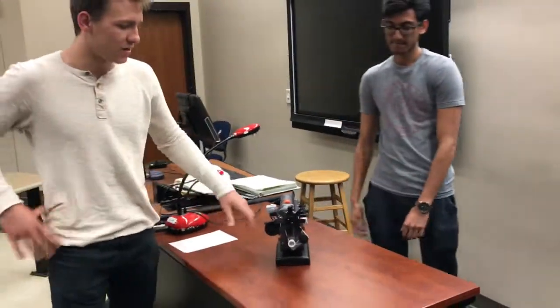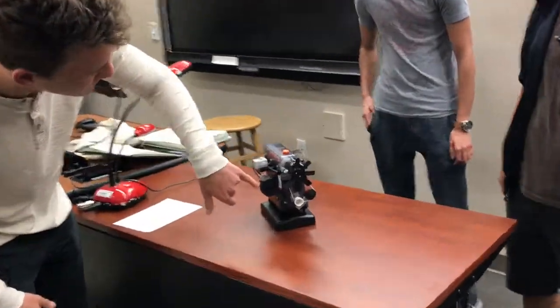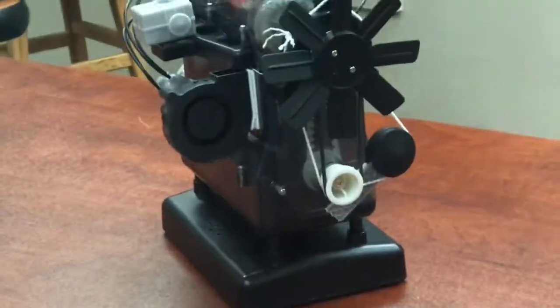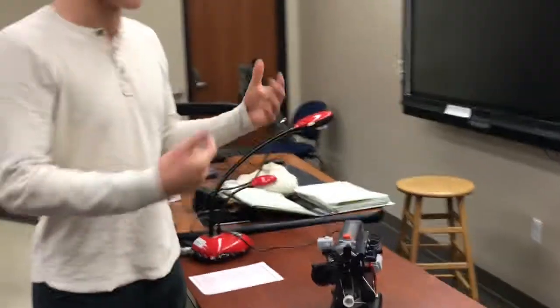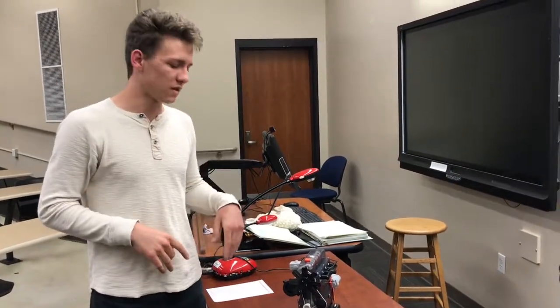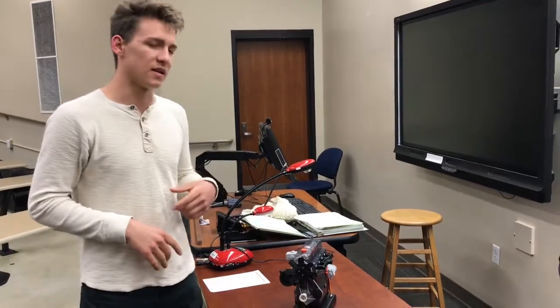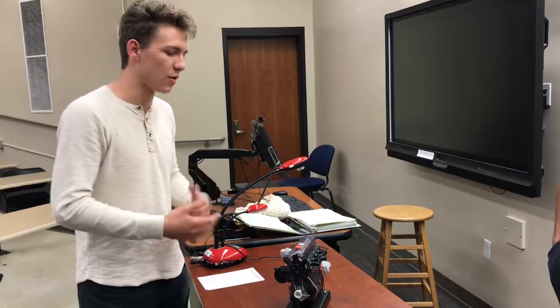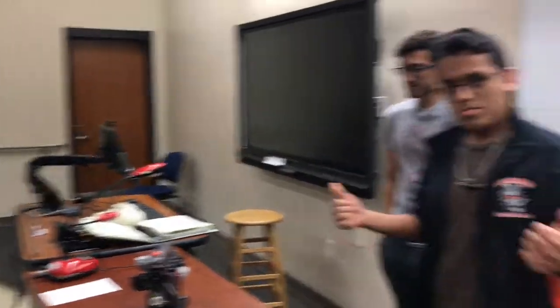And now we'll get into the turbocharger, which is located on the side. A turbocharger is made up of two components, a turbine and an air compressor. What happens is the exhaust gases that are released, as explained in the previous diagrams, are forced into the turbine, and then the turbine causes the air compressor to run, which forces more air back into the motor, and now we will explain what that does for the engine.